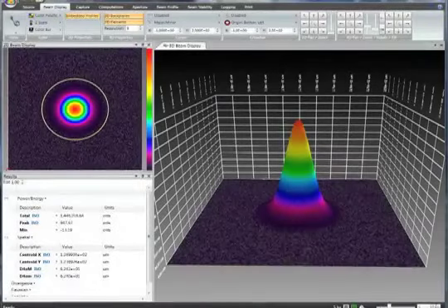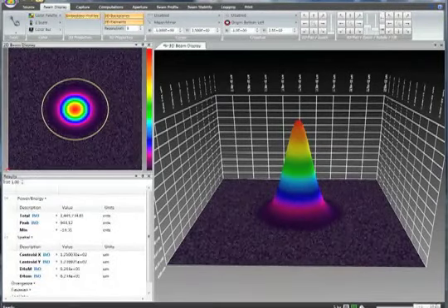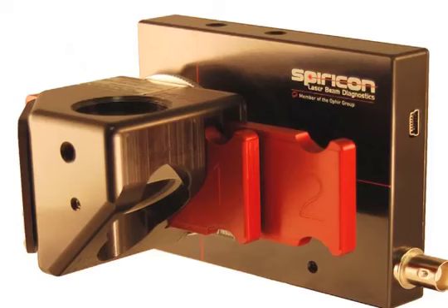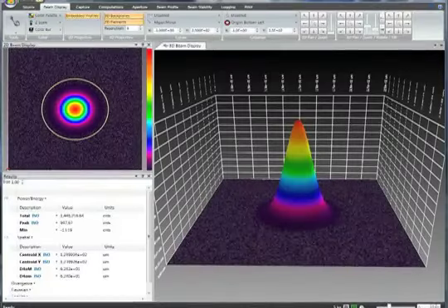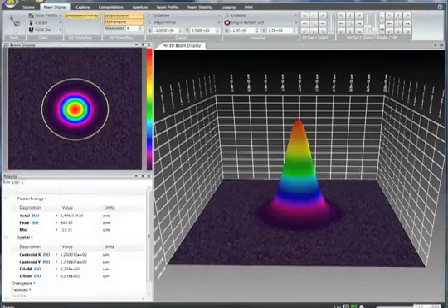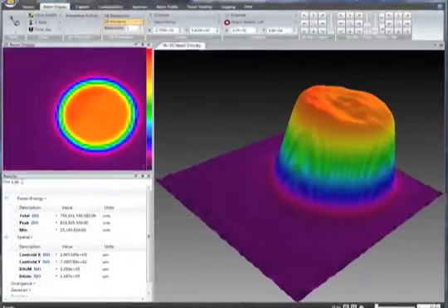This laser joins thin foils for data storage systems. The Spiricon LBS 300 focused spot accessory showed a Gaussian beam profile. Using the correct optics changed the beam from Gaussian to a flat top profile, drastically reducing the rejection rate.